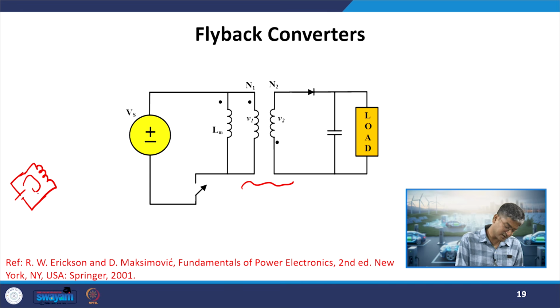What will happen to the current over here? It will be continuously increasing, or the energy stored inside the inductor, half L I squared, will be continuously increasing. Up to how much will this relation be true? Till my transformer core gets saturated.